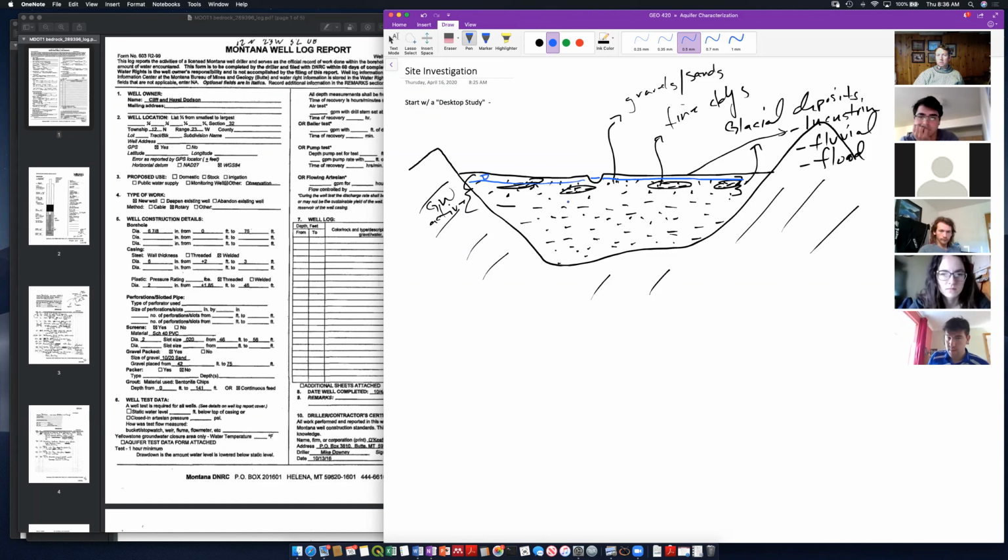And so the job now is going to be coming in here and thinking about what my connection, what does my water table shape look like? Am I dominated by these clay deposits, so I have really low permeability zones? Am I dominated by these gravel deposits, or is it really mixed or is it homogeneous?